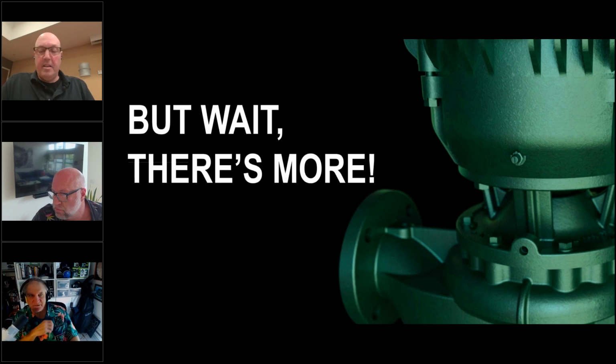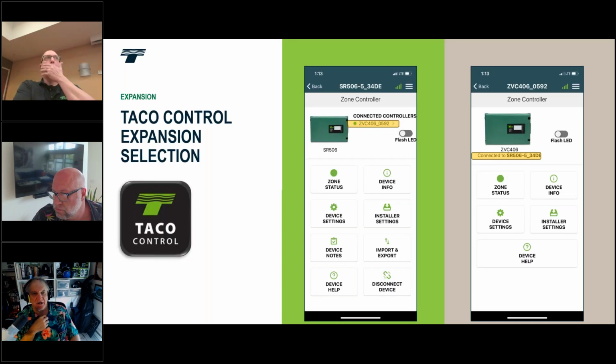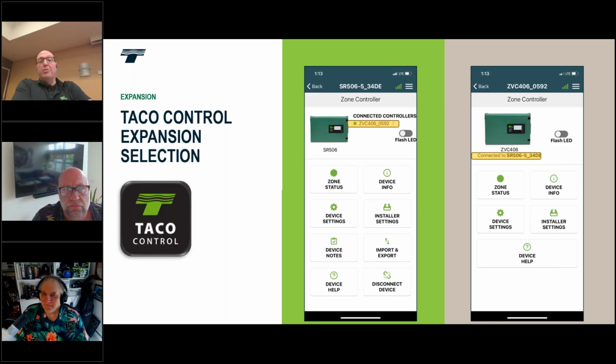A question came up, Dave. How often do we have to update the firmware? My answer on that one is technically never. It's working. Technically never. It's if a new functionality that you wish to use is offered, then you might want to. But that would only be, I think, for new installations, and you want the latest firmware. Make sure you have the latest firmware before you install it. Once it's installed and it's doing what you want, I don't think you'd ever have to update the firmware. I would say not, correct, yeah, unless we came out with a feature that you wanted to use on an older project.